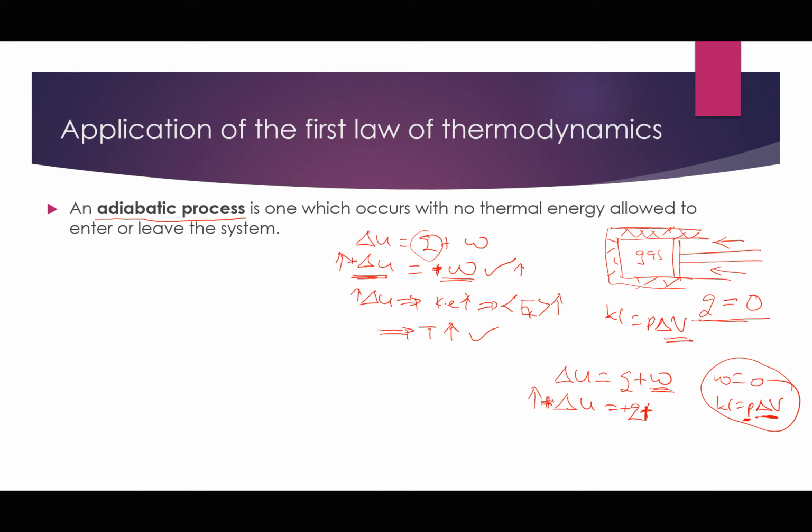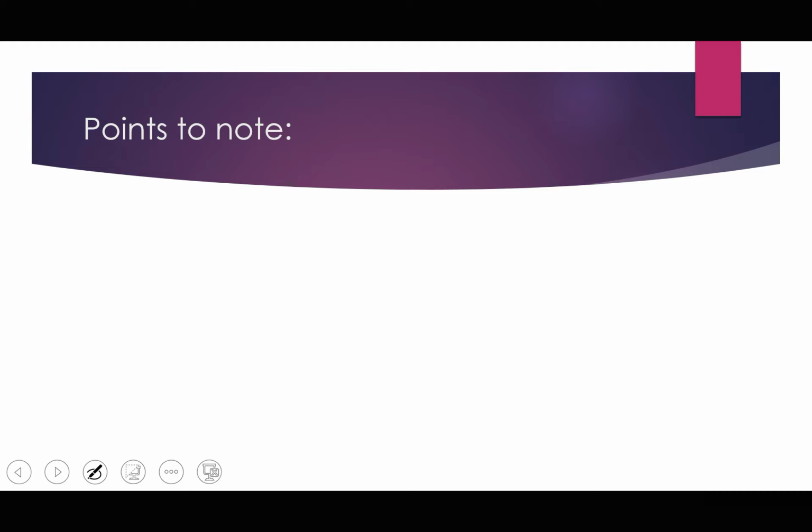So here we have defined another system, which is an electric kettle containing water. The heating element provides heat. That's why Q is positive. Heat is added to the system. We are saying if the kettle does not expand, it means there is no work done. Of course, we don't expect it to be compressed. So that gives us another system. So every time we use the first law of thermodynamics, we shall also be defining the system.